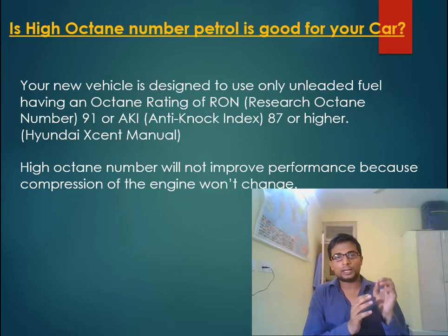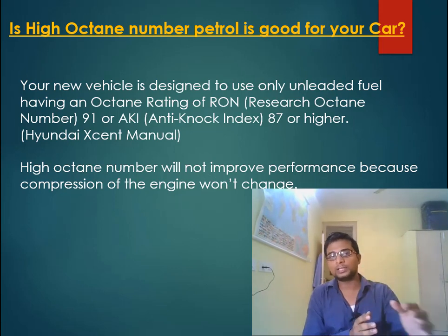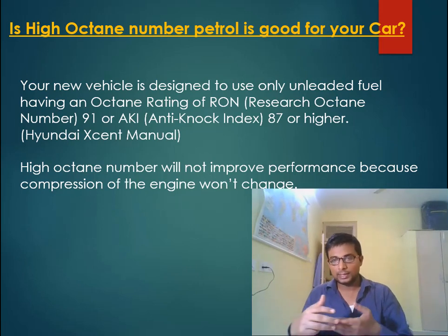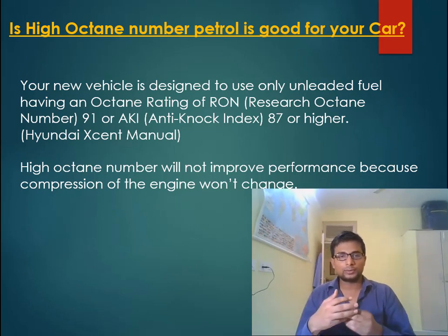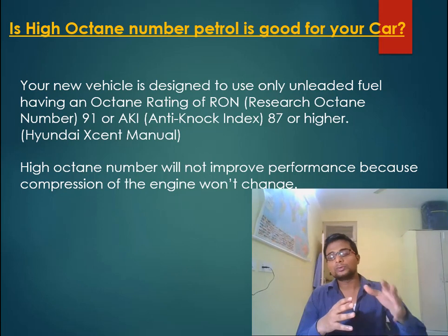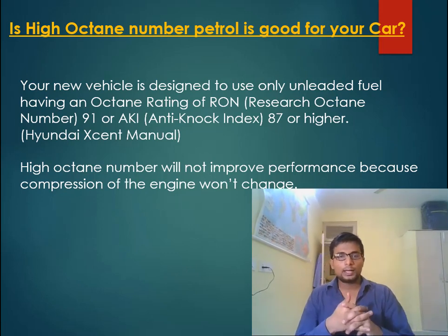A high octane number will be beneficial only when your car compression ratio also increases. So you cannot increase compression ratio. It means for a given car, if that car is designed for say 91 octane number, then you should use only 91 octane number.